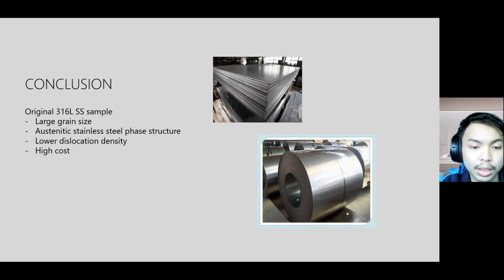Heat treatment is a method of changing the physical properties of metal and improving its suitability for use in a variety of industries by using controlled heating and cooling procedures. Material is heated to the desired temperature and held there for a specific amount of time before being slowly or rapidly cooled down, depending on the type of material, and the process refines the grain microstructure, making it more uniform and workable. It is also used to improve a material's ductility for further machining and to reduce casting stress.